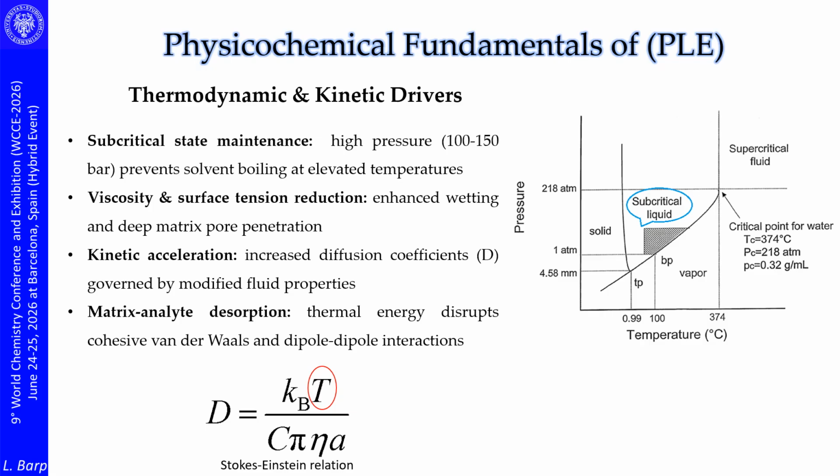When a solvent is heated under these highly pressurized conditions, its viscosity and surface tension drop significantly, enhancing the diffusion coefficients of the target analytes, allowing for rapid fluid penetration into the deepest pores of the solid matrix. Furthermore, the elevated thermal energy provides the necessary enthalpy to efficiently disrupt the strong cohesive forces that bind the analytes to the active sites of the substrate. The ultimate result is an accelerated exhaustive mass transfer rate that traditional ambient pressure methods simply cannot match.